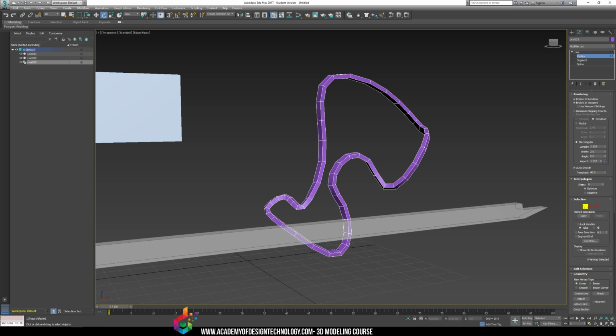Now, I'm going to change this interpolation mode, and that's how we're going to get more polys out of our model. Currently, it's on optimize with 6 steps. If we change the steps amount, you'll notice the polygon count increase, which is great. But it's not really fully optimized the way we want. What you want most of the time, especially if you're going to do movie rendering, is adaptive. What adaptive does is it puts polygons in the right place and the right curves so that everything looks smooth. And you're going to notice this shape.